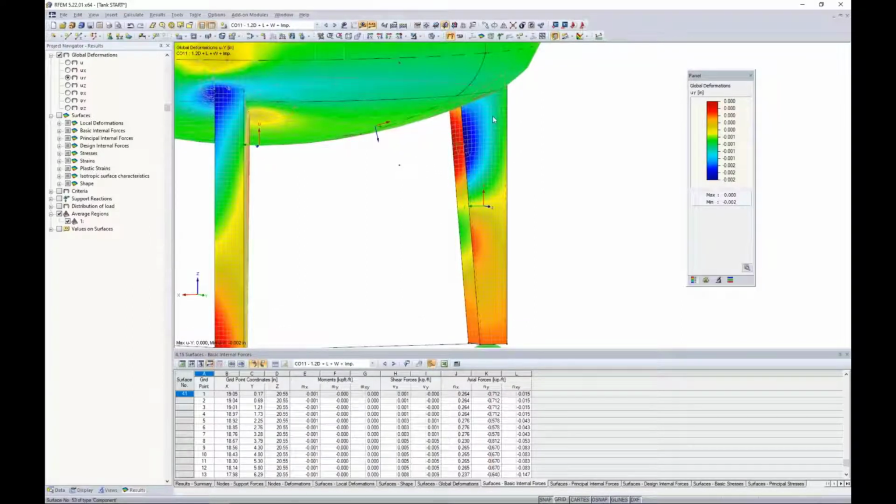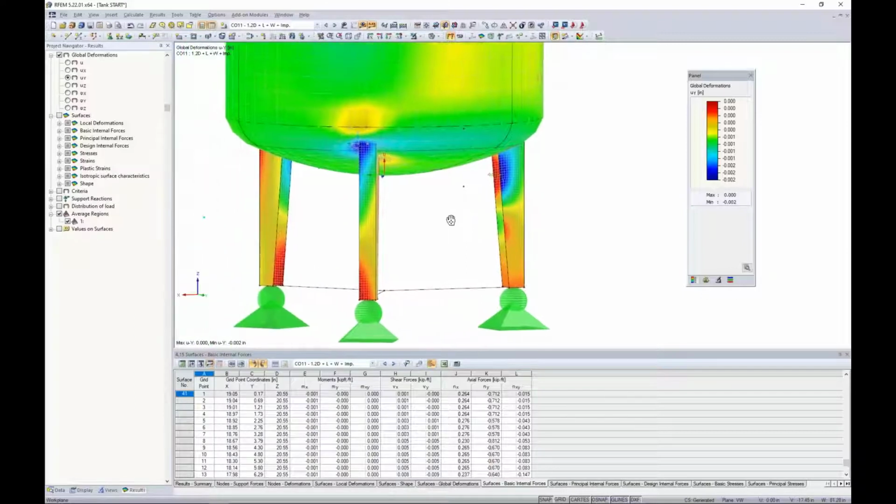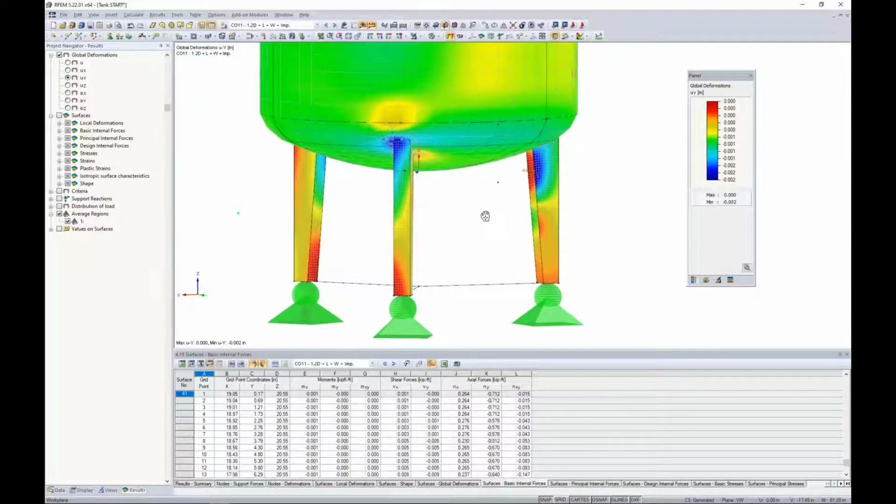We have, ever so slightly, some deflection here in the Y direction that indicates that that mesh was deformed. So possibly with a third order analysis too, we could even see more of those results available to us. But this in general is just one way that we can directly model these imperfections, because again, not everything is going to be perfect as we're modeling here, but rather there will be errors with the manufacturing or installation process.